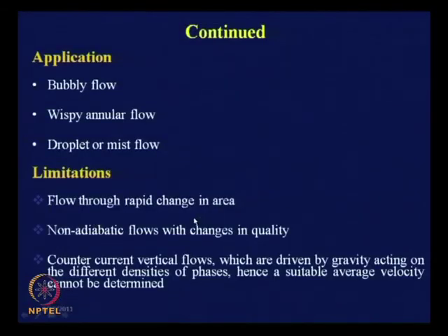So, whenever we encounter any situation where there is flow through a short nozzle or an orifice, where there is rapid acceleration, flow through rapid change in area, under such circumstances, since the equilibrium condition is not valid, we do not have your homogeneous flow theory. So, certain specific cases I would like to read out: flashing of steam water mixture through short nozzles and orifices. We cannot use the homogeneous flow theory.